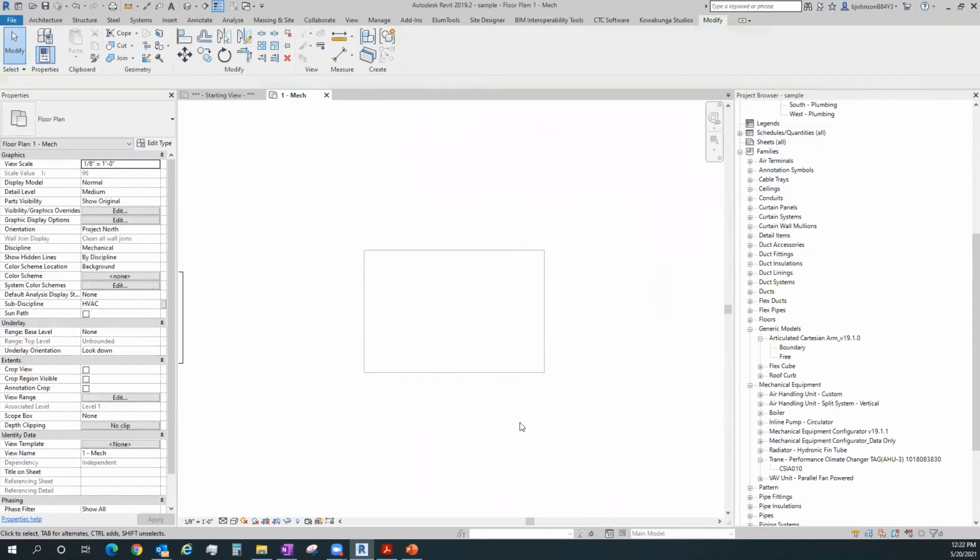I just change that object in seconds to be exactly the size and shape that maybe I need to host. Let's just say I need a new pump or something like that, or a hot water heater or boiler in that model. I could change that to the actual size, go back into the family, add the connectors of type for if it was water piping or if it was ductwork or something like that. I could add those connectors onto the side or the face that I want, maybe a little extrusion, add a few extra parameters to control it and tell it where I want it to schedule that, and I'm pretty much done. So using a template like this to build just about anything is very quick.